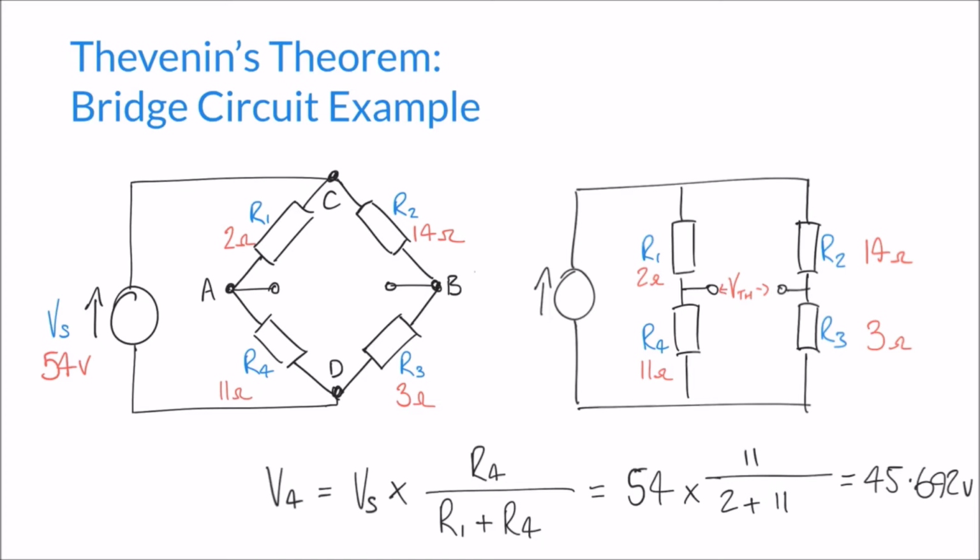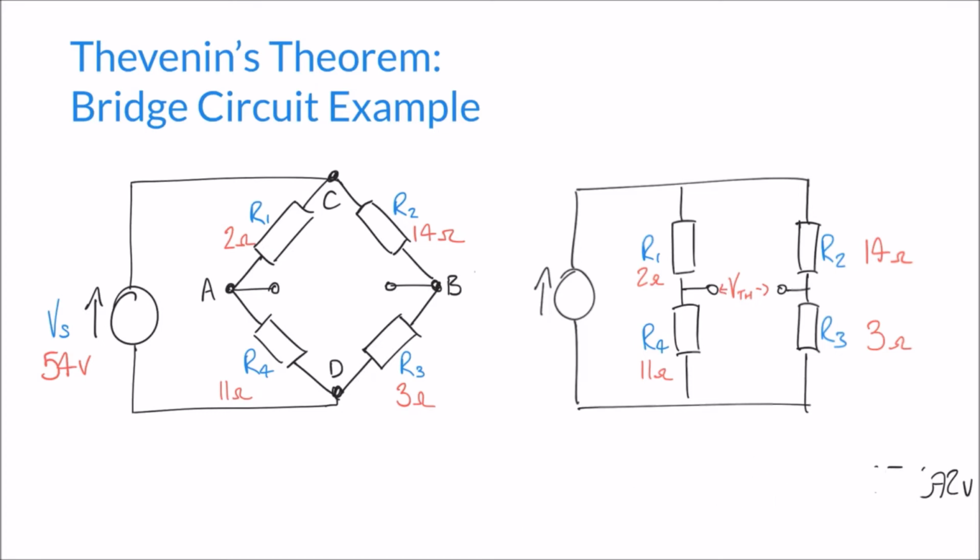We are interested in the voltage at that particular terminal, the midpoint, and that's the same as the voltage across R3, which is this bottom resistor in the divider. And so we can set up a very similar formula. Let's get rid of this one here and replace it with our second potential divider.